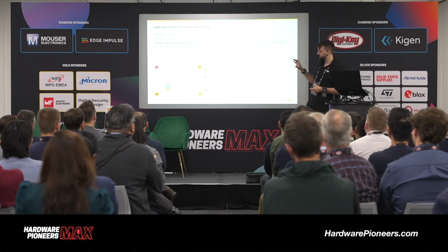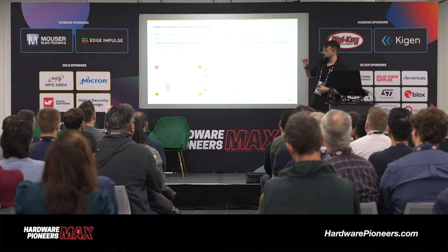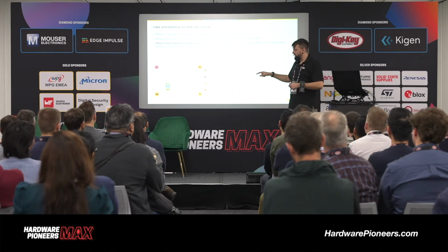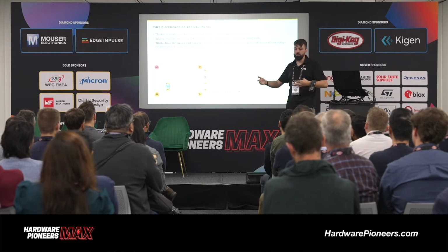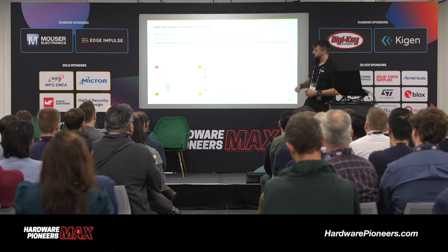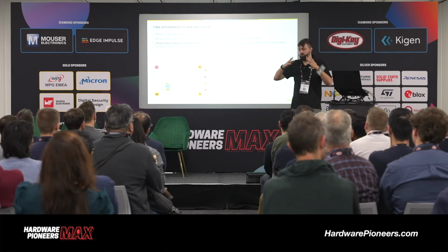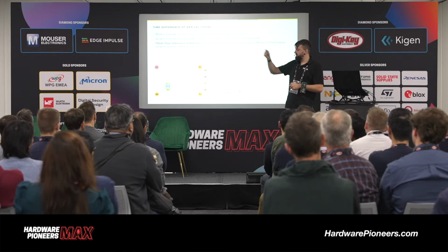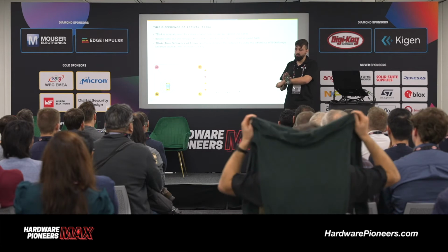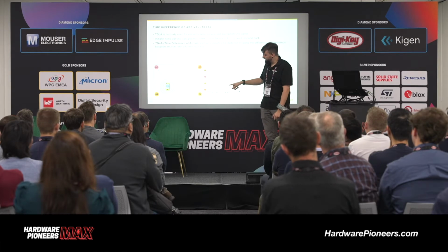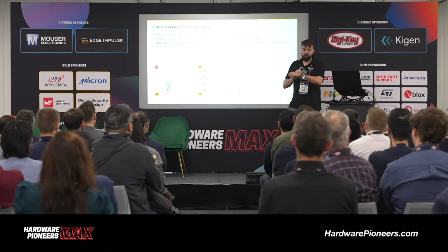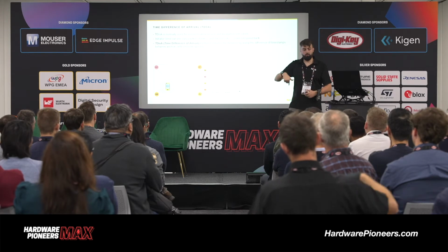The next technique is a little bit different. This time, we use multiple anchors to measure range to one partner device. This would be used in a room environment where you have anchors and a grid of ultra-wideband devices, and where you want to have your position in the room. So you have 4 anchors, each placed anywhere in the room. They send out messages, and your device reads these messages, and then from the difference in reception time, your device can calculate where it is in the room.